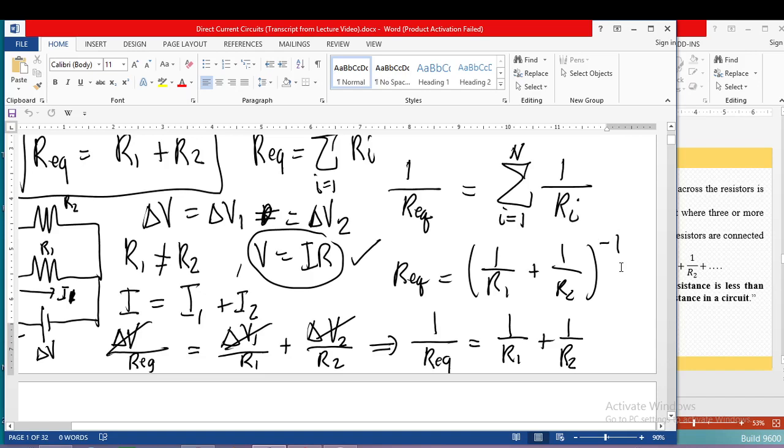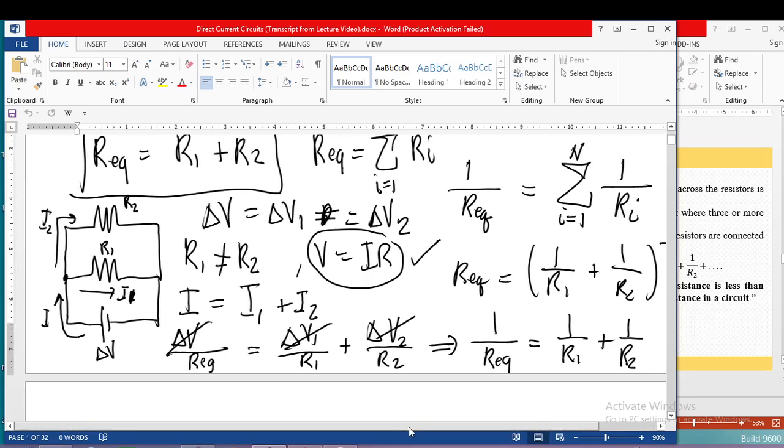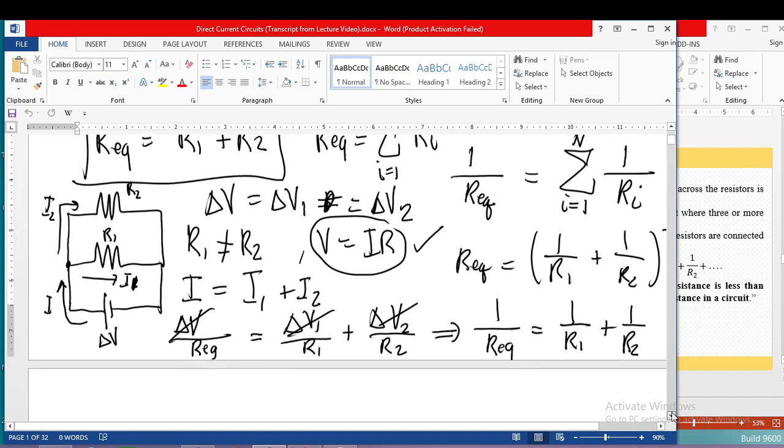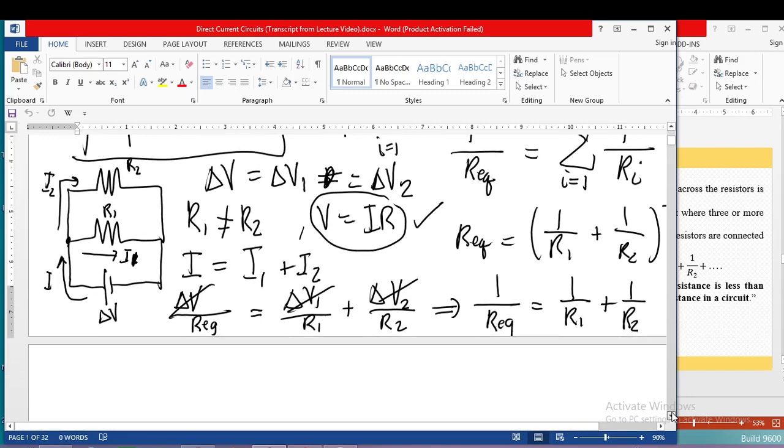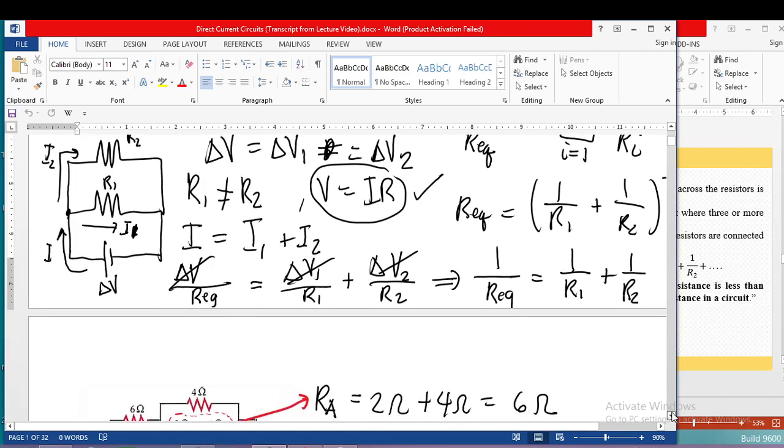And if you have two or more resistors in your circuit in parallel, you just have to sum their reciprocals, and then find the inverse. Okay, so yeah, I think that's the review of your circuit reduction technique, because you already know the formula for the series and parallel circuit in terms of the equivalent resistance. But for series-parallel combination, we still get the same formulation. It depends on which is in series and which is in parallel.